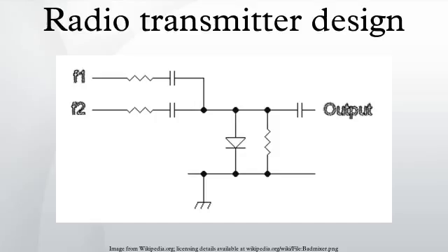Solid state devices, either discrete transistors or integrated circuits, are universally used for new transmitter designs up to a few hundred watts. The lower-level stages of more powerful transmitters are also all solid-state. Transistors can be used at all frequencies and power levels, but since the output of individual devices is limited, higher power transmitters must use many transistors in parallel, and the cost of the devices and the necessary combining networks can be excessive. As new transistor types become available and the price drops, solid-state may eventually replace all valve amplifiers.